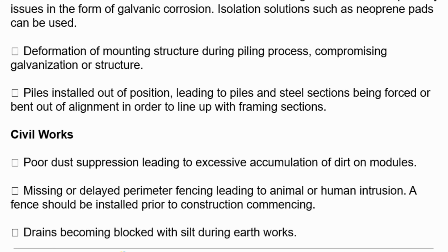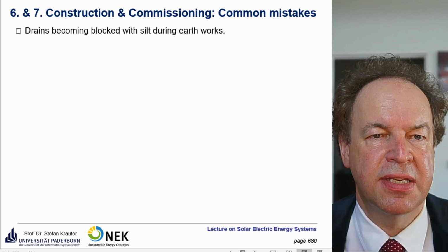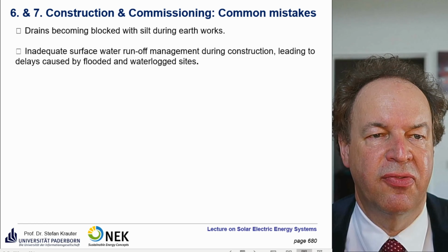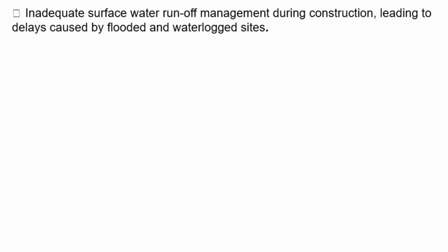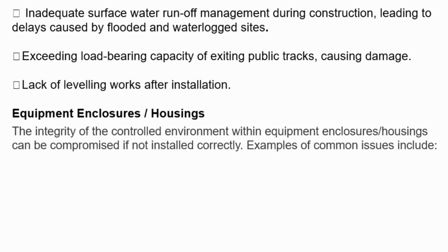Drains becoming blocked with silt during the earthworks. There could be some flooding then. Inadequate surface water run-off management during construction, leading to delays caused by flooded or waterlogged sites. Excessive load on the load-bearing capacity of existing public tracks, causing damage. Lack of leveling works after installation.